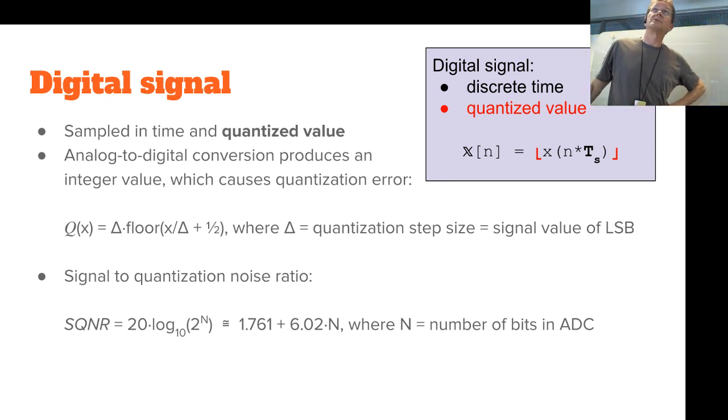If you have some music, you want to have something like at least 80 decibels of dynamic range for that recording, and that gives you that you need at least, say, 12 bits would be almost enough. It's 70-some dB. Not quite yet, but still nearby. 12 bits is okay for audio like speech or something like that.